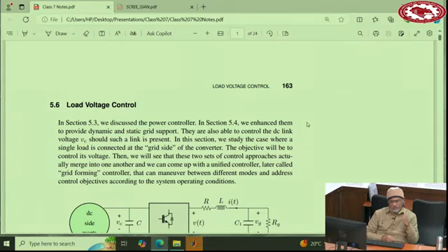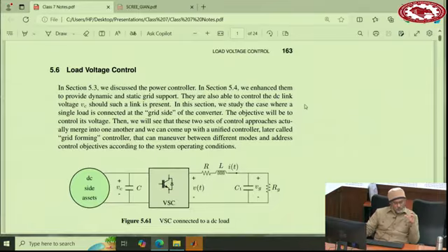We considered one converter which connects a DC side to another DC side. Especially on side B, we considered voltage. We call it grid voltage, and we controlled power. So we controlled power going from side A to side B. This is a situation where you have either a power grid or a microgrid on the B side, on the right side here, or for instance you have a battery you want to charge. So again, the battery supplies a voltage.